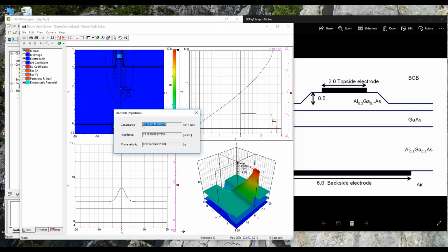The first one is a low frequency, like a bulk circuit element capacitance. So there will be a capacitance between these electrodes. It will depend on how long the electrodes are. And so it's just been calculated here that we're going to get about 1.2 picofarad for every millimeter that the electrodes are long. And that will apply as long as our electrodes aren't long enough to become a significant number of the radio frequency wavelengths.